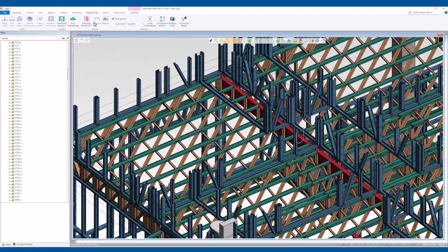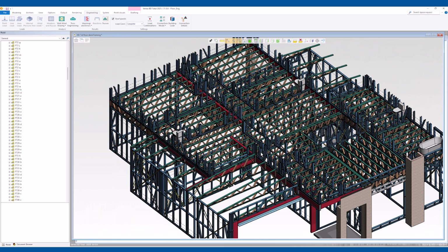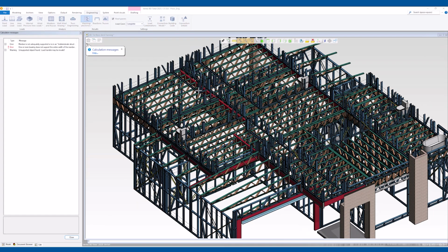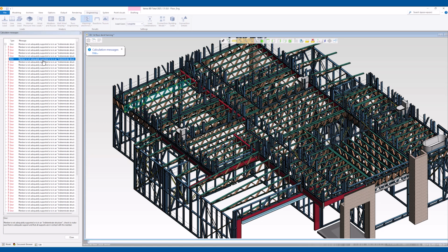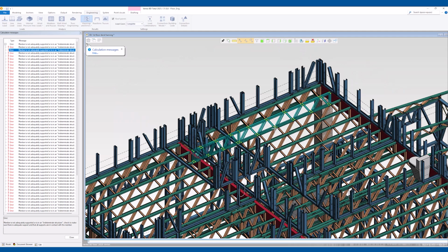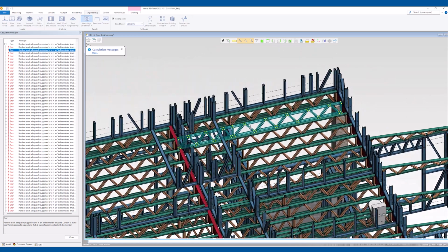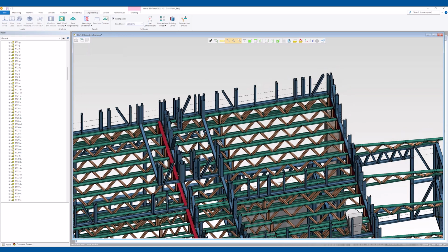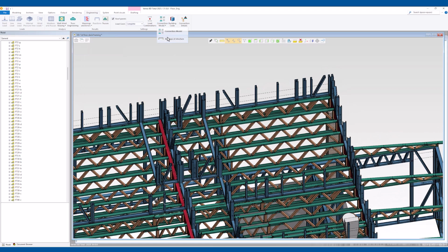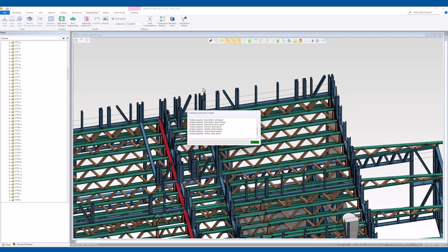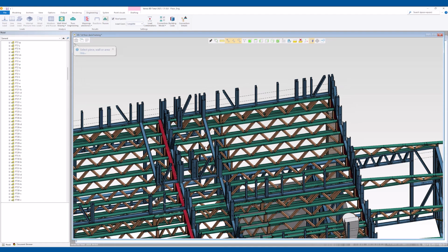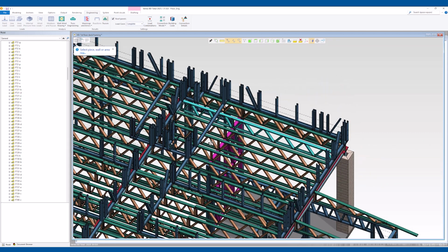Let's jump into the 3D model and open the warnings and errors list. So we can click each of the errors listed here, and in the 3D model, the problematic area will be highlighted as well. So we can see the error says this structure doesn't have enough support, and we can use this bearing structure function to check the support of each structure.